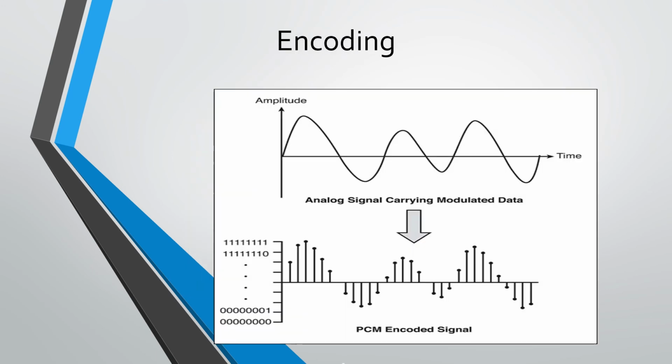Encoding is a process of representing the sample values as binary numbers in a range 0 to n. The value of n is chosen as a power of 2 depending on the accuracy required. Increasing n reduces the step size between adjacent quantization levels and hence reduces the quantization noise. The downside of this is that the amount of digital data required to represent the analog signal increases.